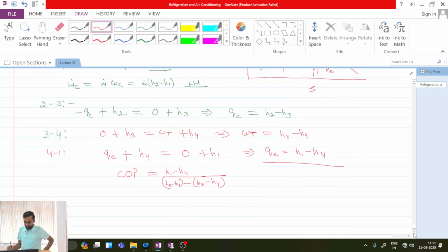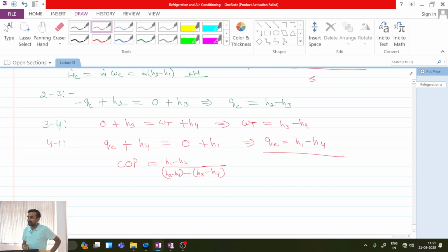Okay, you tell me, turbine is nothing but a steady flow device. So here we will be having open work. What will be open work? Work done in an open system, shaft work, minus integral of VdP, where V, what is V? Specific volume.